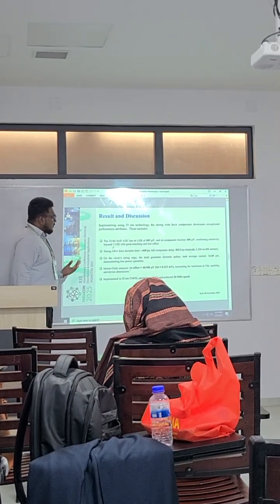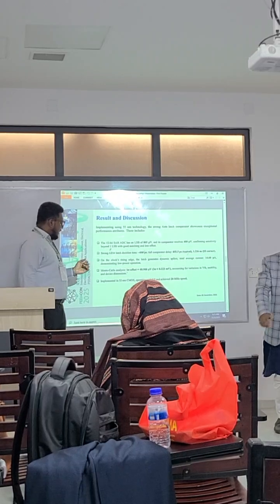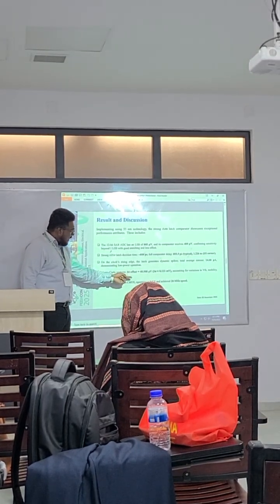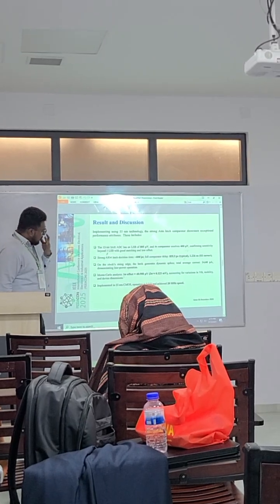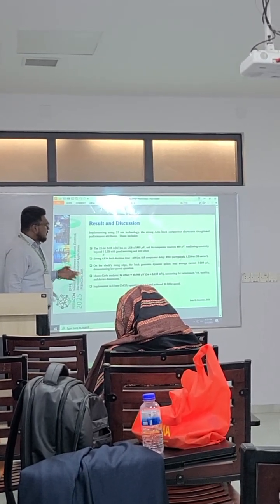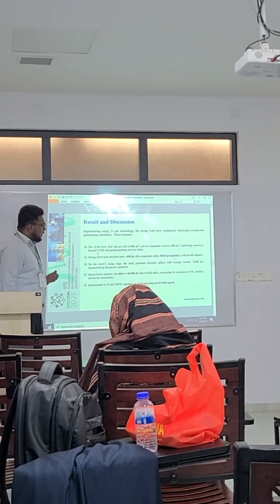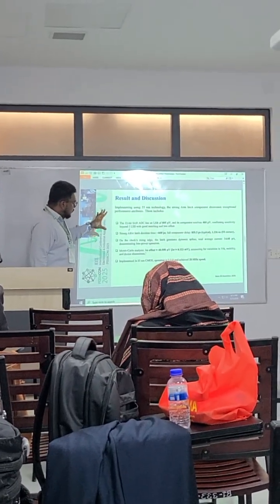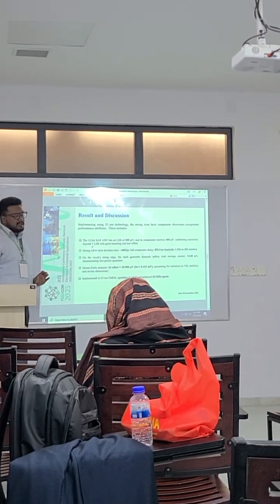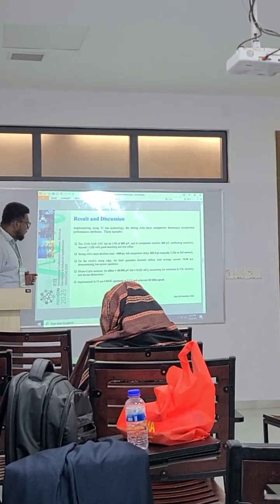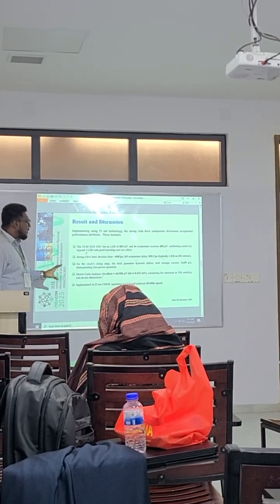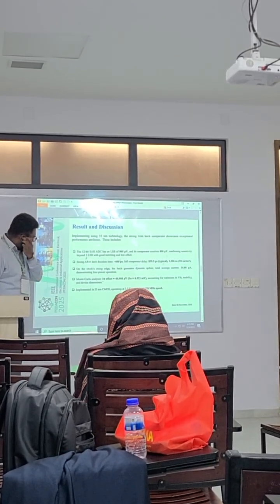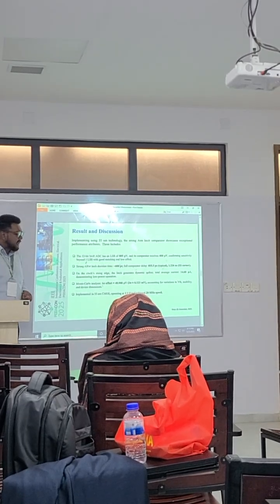In terms of the Monte Carlo analysis, along with the preamplifier, the latch has one sigma offset of 40.908 microvolt. So the 3 sigma is around approximately 0.123 millivolt. So again, this work has been implemented in the 55 nanometer CMOS technology. And the circuit operates at 3.3 volt, and we have made the circuit work at 220 megahertz speed.